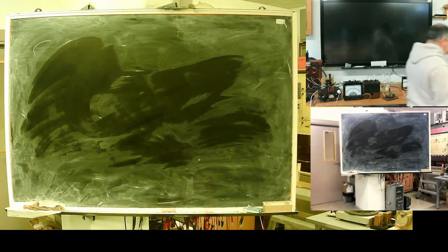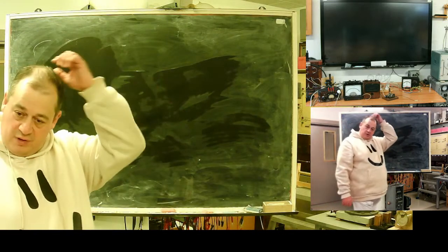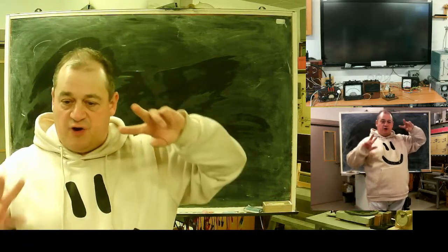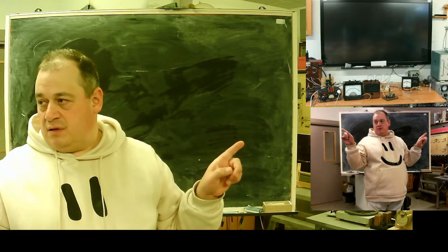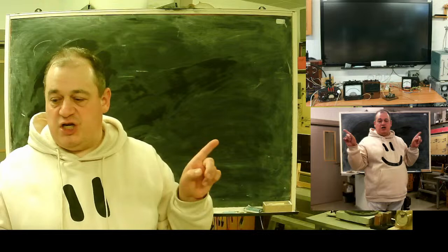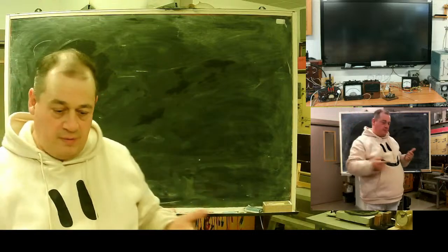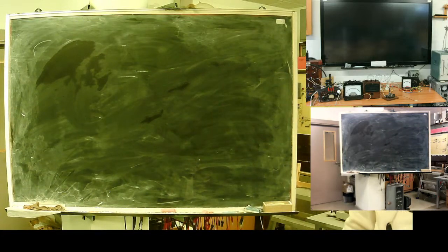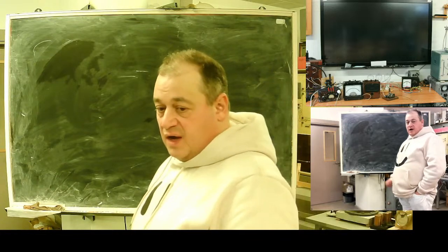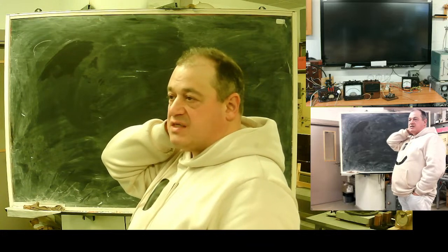Zero sequence flux, because the sum of phase fluxes will be triple, not zero, goes from the windings, then goes outside along with the machine rotor and closes around. Kind of nomad flux. It's a flux in dissipation.